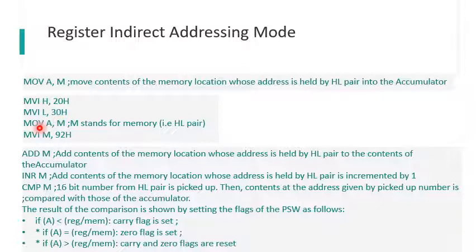The instruction in the third line tells the microprocessor to look at the address 2030 and load the content stored there into the accumulator. As we assumed that the memory location with address 2030 was loaded with the number 25H, which was stored previously in that address location, the microprocessor will copy it and paste it in the accumulator, and hence the accumulator will contain 25H.